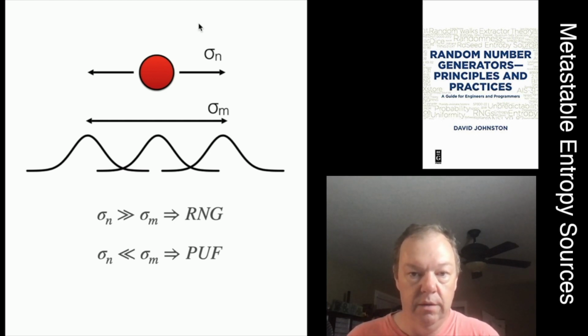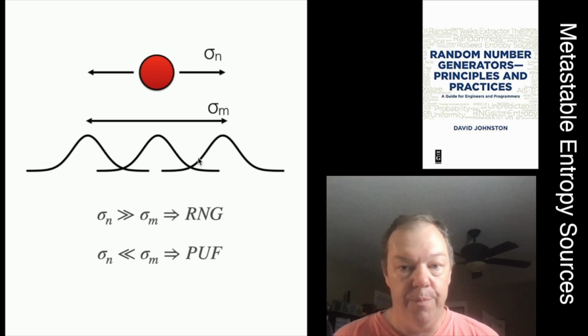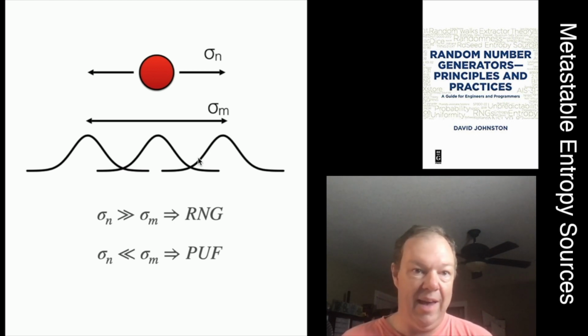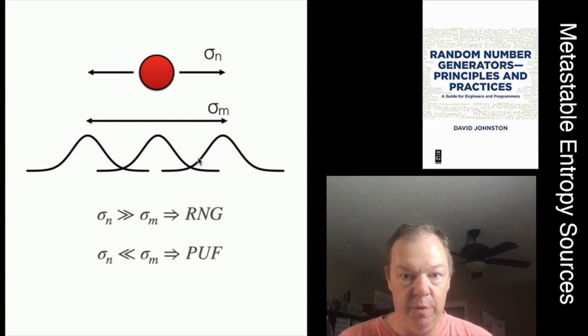Then we've got the hill itself, which could be in the middle, it could be on the left, it could be on the right. Its position, again, is normally distributed, and we call that sigma m. So the n is for noise, and the m is for manufacturing noise. In a digital circuit on a chip, that manufacturing noise is all the variation of dopant atoms and layer thickness and things that vary when you manufacture silicon. There's always some variation. And in fact, the smaller the device is, the greater the variation. You think of one atom being here or there, creating a difference. As the device gets smaller, it's made of fewer and fewer atoms. That one atom has a bigger and bigger influence.